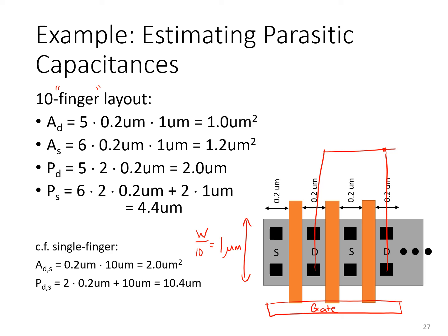And by alternating drain and source connections, in this way, you end up with a 3-terminal device that comprises all 10 of these sub-transistors in parallel. So you effectively have now one transistor with 10 times the width, which is the same as the transistor that was shown in the last slide. So here is the gate of this transistor, here's its source, here's its drain. And somewhere around this structure, you'll also have to provide a body contact, of course.